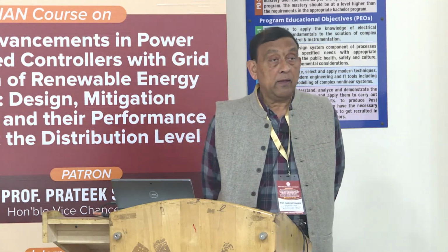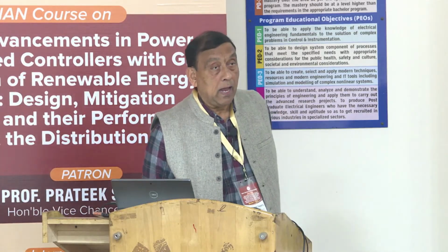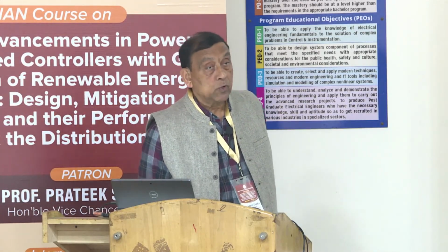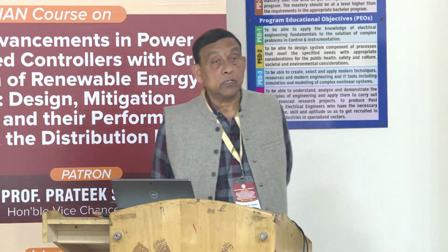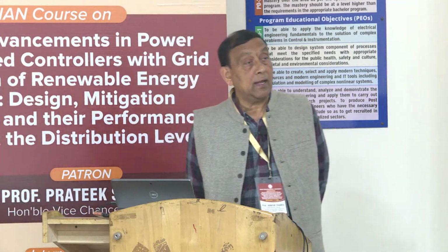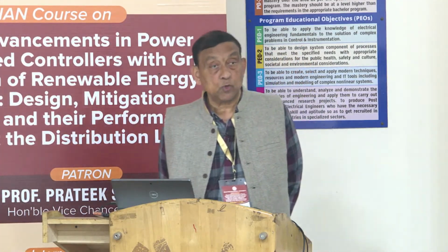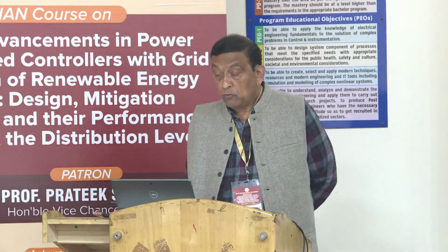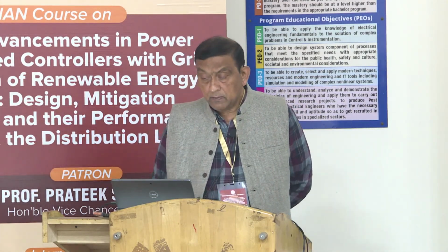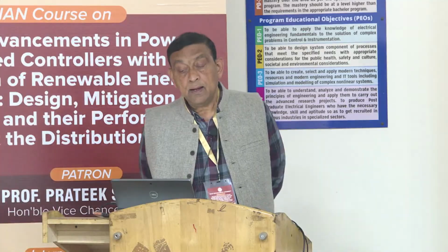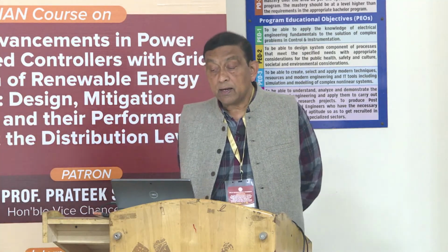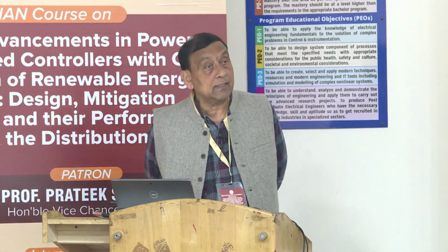If we have harmonics, high frequency is there, so hysteresis losses are proportional to the frequency, while eddy current losses are proportional to the square of the frequency. So we will see perhaps again this a little bit.